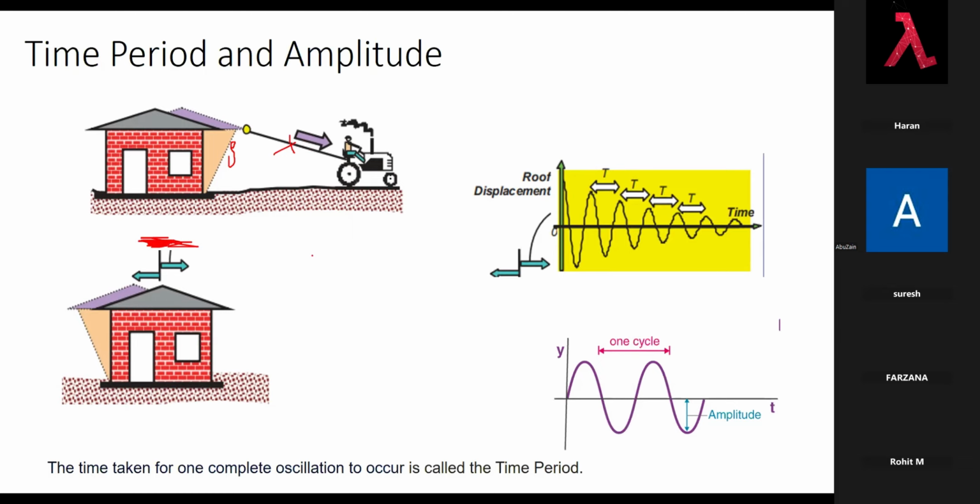So that displacement, we can plot it here, okay? We plot it like a graph. So this x-axis is your time, and your y-axis is your delta. Did you understand this graph? How we got this graph? Because my building is moving left right, and each cycle it is reducing because of some damping. We'll come to that one point.